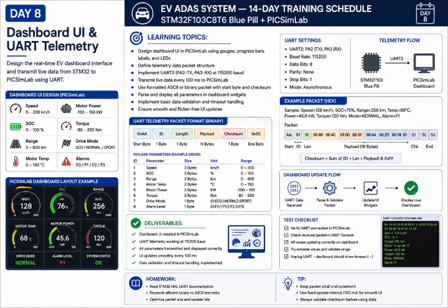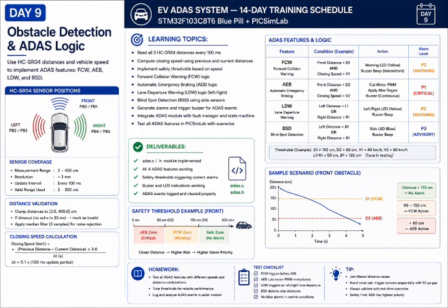And coming to day 8, I developed the ADAS engine using ultrasonic sensor data and vehicle speed. The system calculates time to collision and generates collision warnings. Blind spot detection and parking assistance were also implemented in this project. Alarm hysteresis was used to avoid unnecessary repeated warnings.